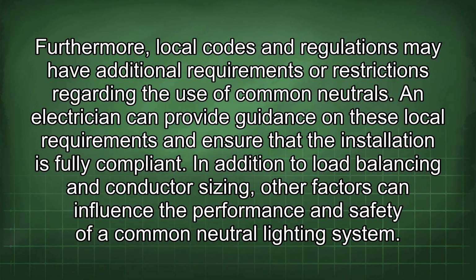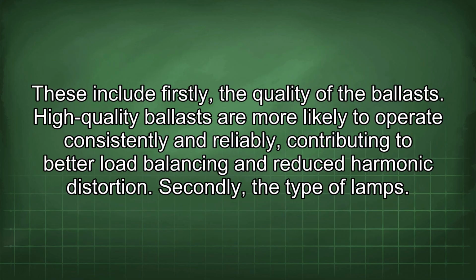In addition to load balancing and conductor sizing, other factors can influence the performance and safety of a common neutral lighting system. These include, firstly, the quality of the ballasts. High-quality ballasts are more likely to operate consistently and reliably, contributing to better load balancing and reduced harmonic distortion.